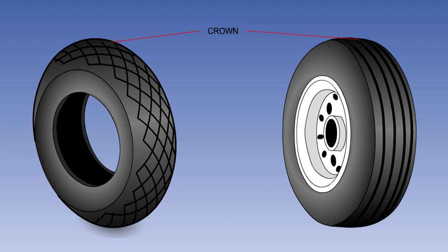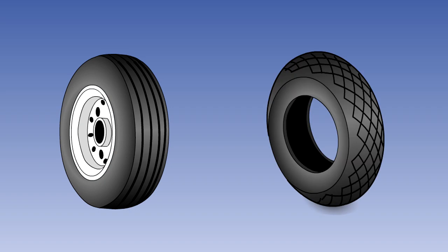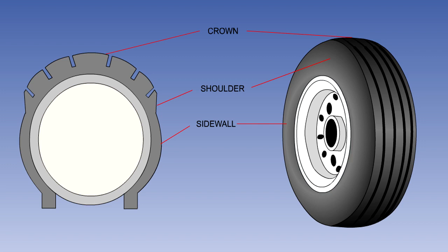The tyre is divided into regions or sections, as illustrated here. The tread of the tyre is situated in the crown and shoulder section. It is worth noting that the term tread is applied irrespective of whether the rubber is plain and smooth or moulded in a block pattern. The sidewall allows the tyre to be flexible, and the bead is seated inside the flange of the wheel.